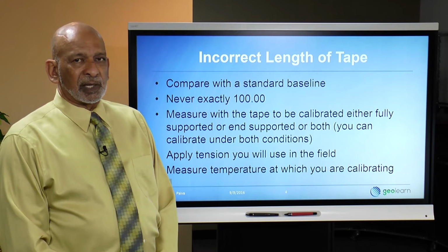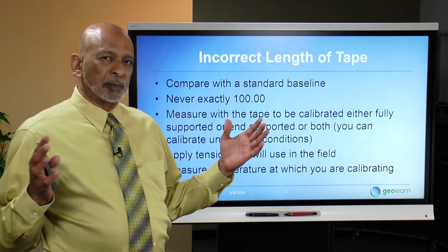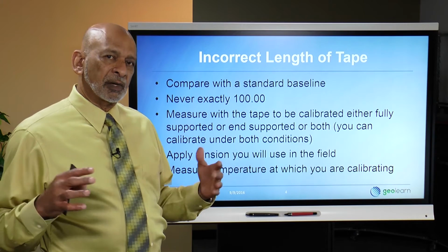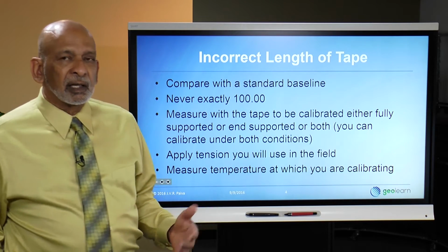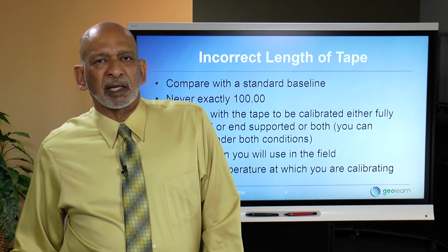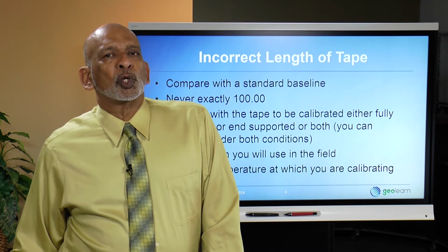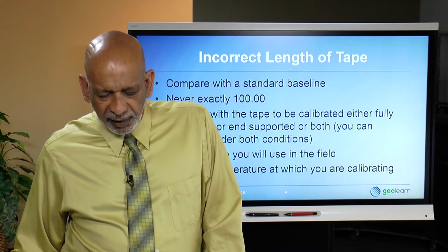Keep in mind, when it's 10,000th of a foot, even warming and cooling of the building, meaning the expansion and contraction of steel and concrete in the building, could cause that baseline distance to vary. So very rarely is a calibration baseline that's calibrated to 10,000th of a foot standard for very long, meaning they're constantly recalibrating it.